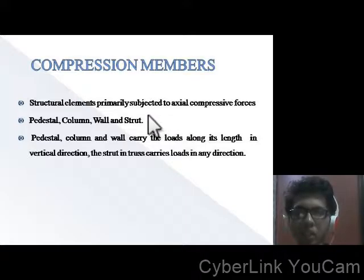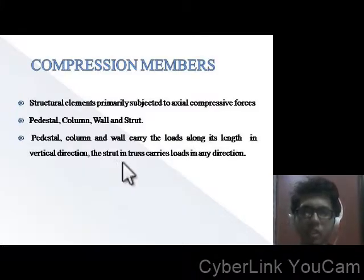The main examples of compression members are pedestal, column, wall, and strut. Pedestals, columns, and walls carry the load along their length in the vertical direction, while the strut in a truss carries the load in any direction.